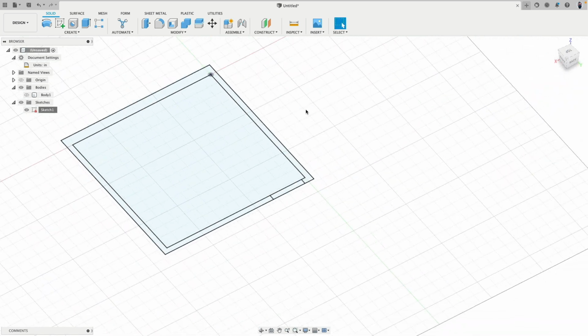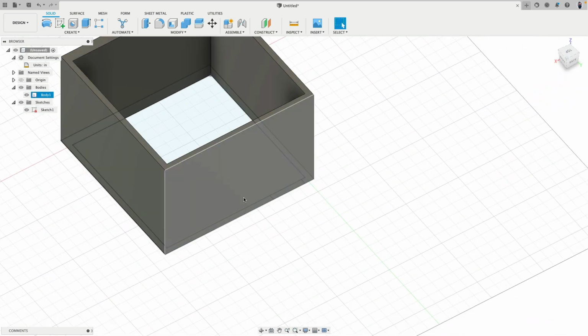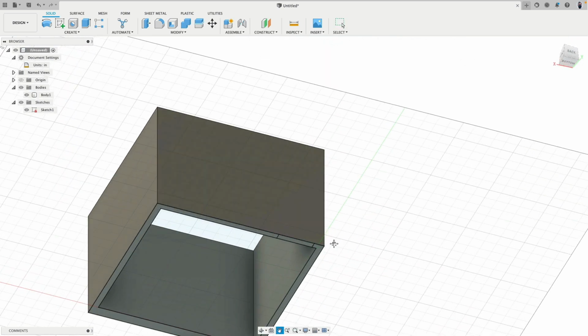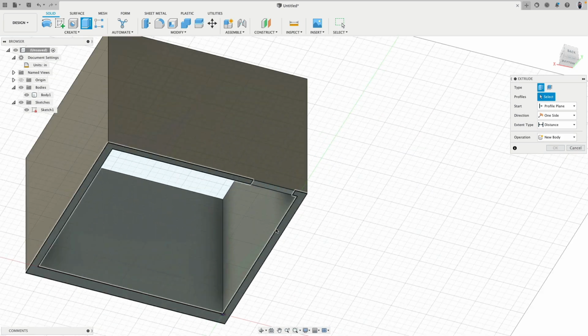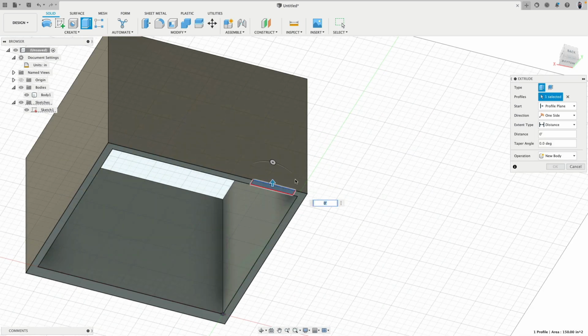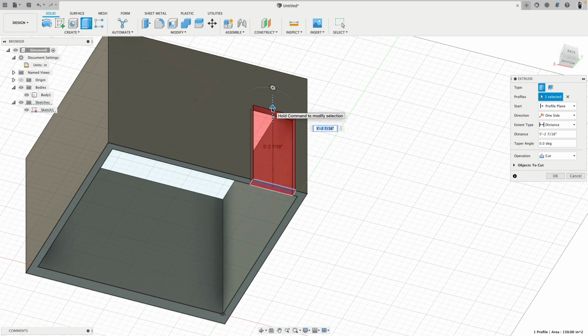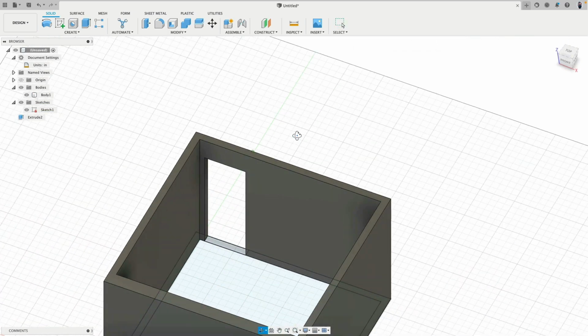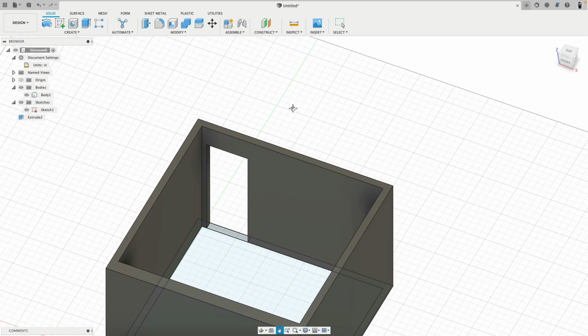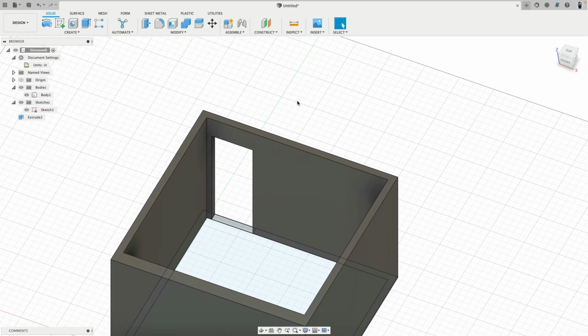There we are. Now, let's take a look at this. This is our wall, and we would like to cut in the space for the door. So we go extrude. There is our sketch. And when I extrude up, you see this extrusion goes into the wall, and automatically the software thinks we want to cut something out to the height of 80 inches. Again, dimensions slightly simplified. Not too difficult, no? Cool. Okay.